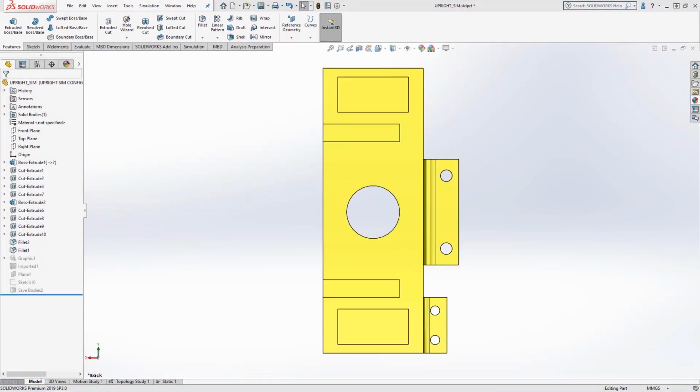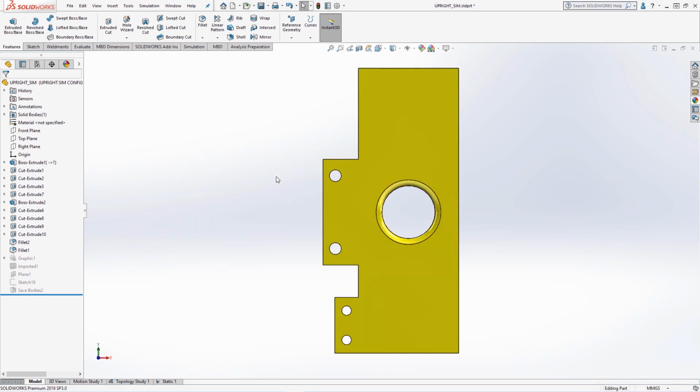A more representative model includes the brake and steering arm brackets, as well as pocket cuts for the rose joint wishbone connections, and an access slot to secure the nut and bolt through the joint. This takes into consideration manufacturing and assembly constraints. The rear face also has a flush finish for simpler machining and also a small fillet for clearance.